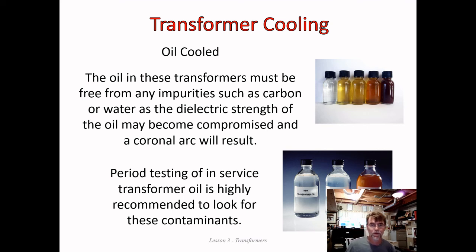So that's the second paragraph there. Periodic testing of the in-service transformer oil is highly recommended to watch out for any contaminations. As that oil ages and gets contaminated, it loses its dielectric value.